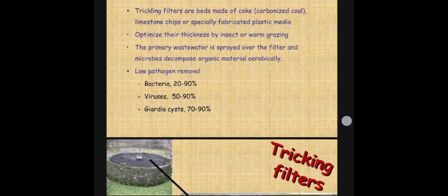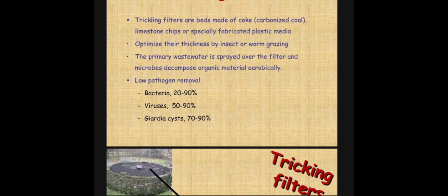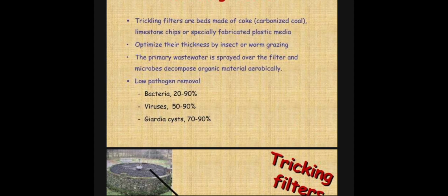In this process, as in the third point, the primary wastewater is sprayed over the filter, and the microbes decompose organic material aerobically. Due to this, 20 to 90% of bacteria will be removed, and 50 to 90% of viruses are also removed.